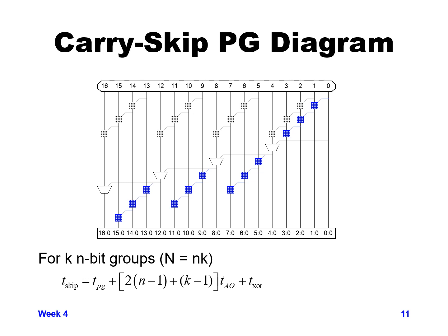If, on the other hand, let's say we had a 64-bit adder and we broke it up into 8 groups of 8, instead of going through 64 for a ripple adder, the carry skip adder with an 8 and 8 would give us 8 minus 1, 7 times 2, plus an additional 8 minus 1 is 7.